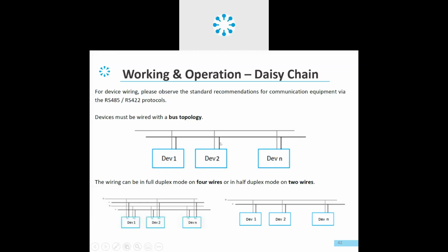Normally what happens is, from here we used to take another chain to another device here, and we keep on carrying this chain like this. This creates a star network. We used to do this in fields because our device cannot be merged in this chain. So it's not a daisy chain, in fact. So a daisy chain should be like this. Your devices should be coming in sequence like this: device ID 1, 2, 3, 4, or whatever has been assigned.